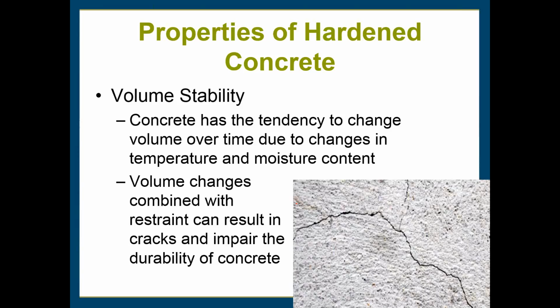Right, yeah, reinforcing fibers, if they don't have a similar coefficient of thermal expansion, can be an issue, but usually it's not that type of restraint. It's restraint in the sense where, let's say you pour a slab on your plant floor, and you pour it against the floor, or you have some sort of bond breaker. When that slab tries to shrink, which it tends to do when it hydrates and cures, the friction between the slab and the floor comes into play. That's a form of restraint. So if it's not an adequate bond breaker that enables that concrete to move slightly, then you might get some cracking there due to restraint. That's restraint against an outside body as opposed to reinforcing or aggregate.